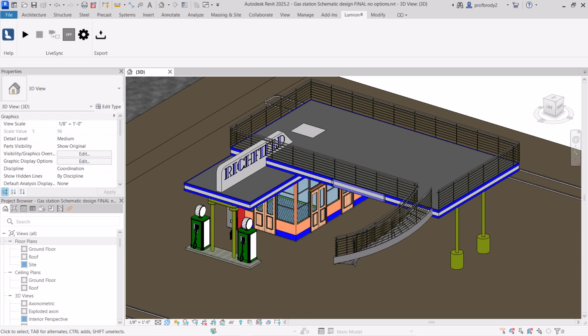But basically, Lumion respects Revit materials generally. So if you apply any kind of material in Revit, Lumion will recognize it. And there are some funny situations that you'll run into where the materials don't apply correctly. This is particularly true for mapped material. So let's say you used an image in Revit to create a material. Sometimes those maps don't show up correctly in Lumion. You can just reapply the map in Lumion.